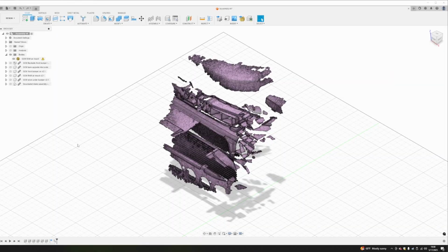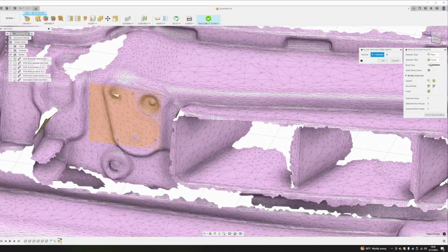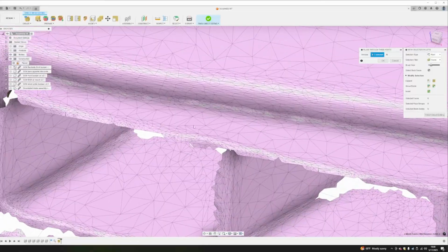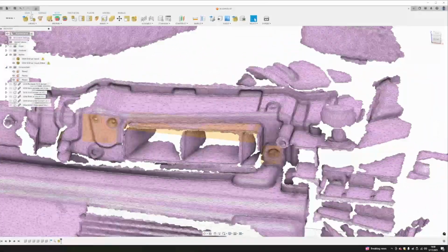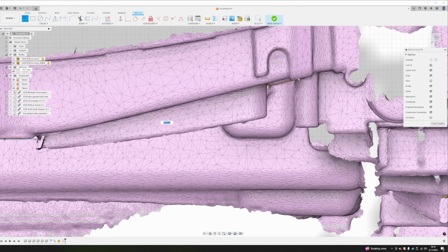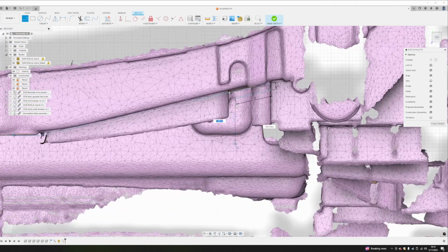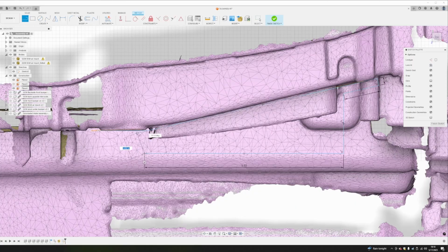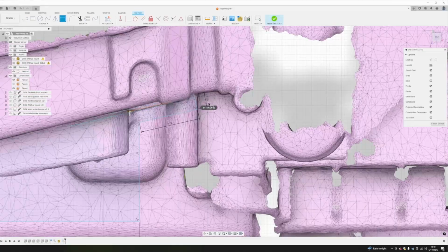And go. So I found when you first start a 3D scan, you can actually go into the scan, the mesh body, and it's called direct editing in Fusion. But when you do that, that lets you select the face of the mesh. So as you saw just a second ago, I went through and made 3 planes through 3 points on the mesh itself. And then I was able to pick one of those planes and start doing the sketch that I'm doing right now.